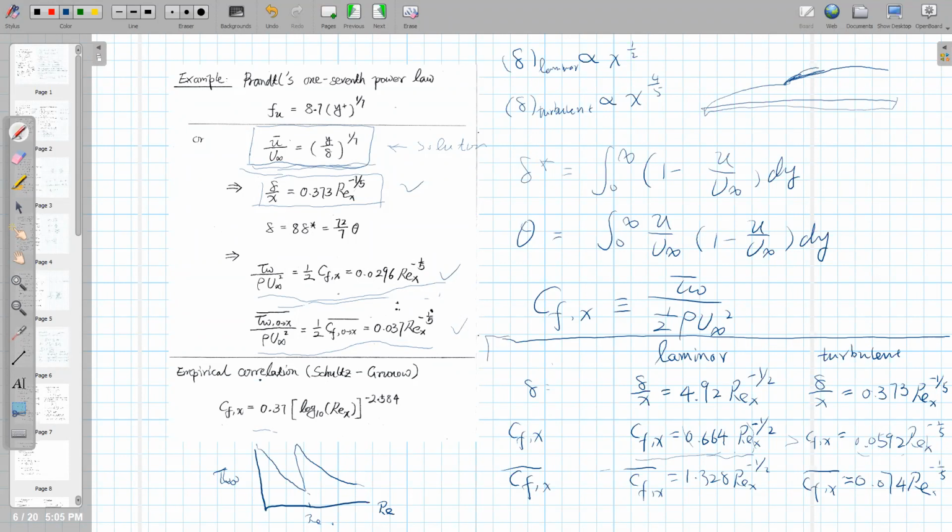No. The important thing is this final result: in the laminar cases and in the turbulent cases, how the coefficient is changed, how this power of -1/2 is changed to this power of -1/5 instead, and how this delta x is increasing in the turbulence. All right, so this is the hydraulic performance of the turbulent boundary layer. So what is the thermal performance?